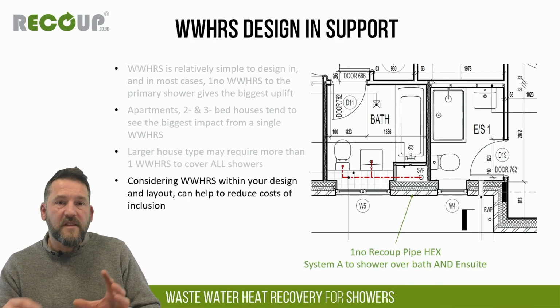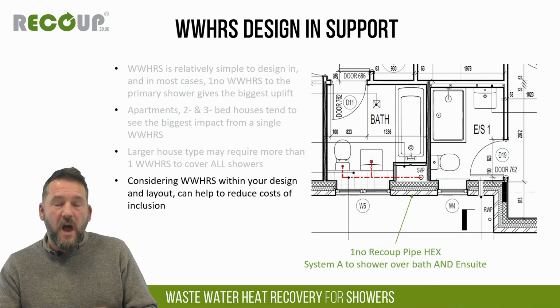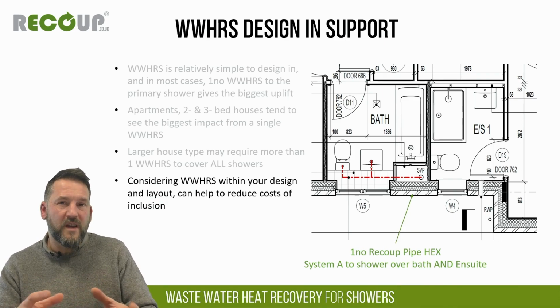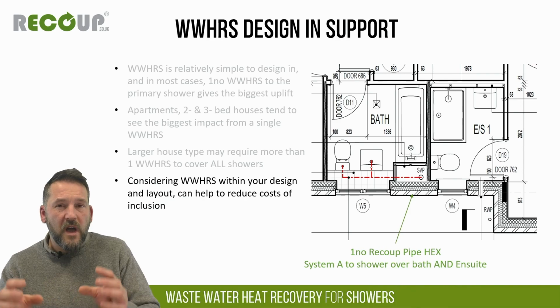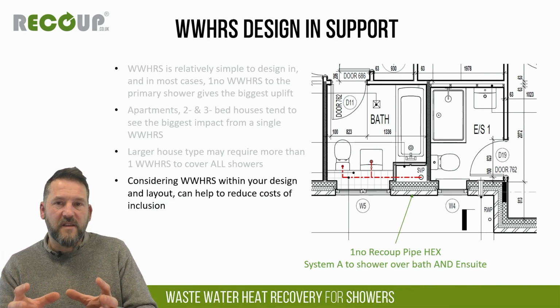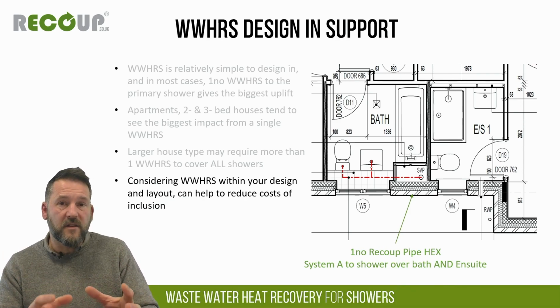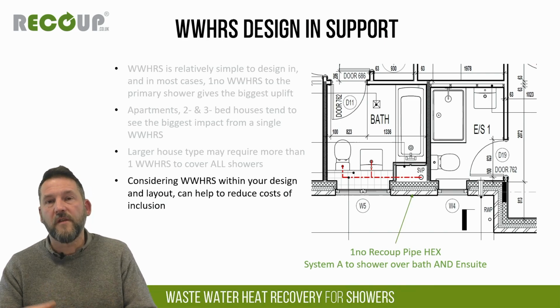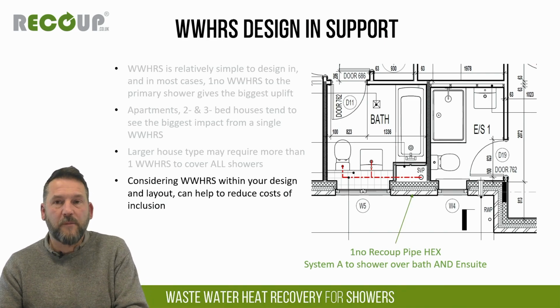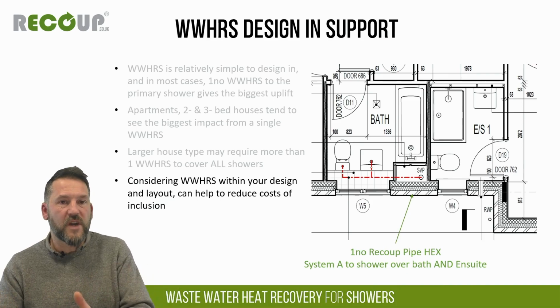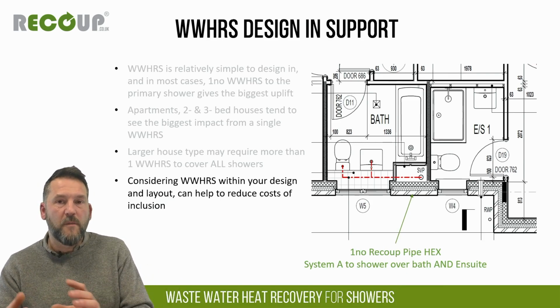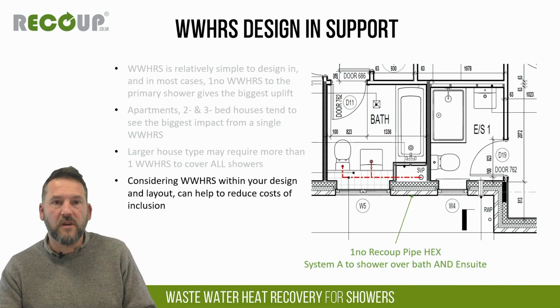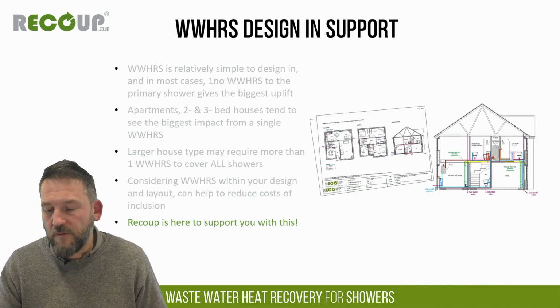And considering wastewater heat recovery early on, certainly if you engage with us early on, we can advise on tweaks and things that we know to make sure you get the best out of wastewater heat recovery, or certainly the least cost for wastewater heat recovery. So for instance, the obvious choice would be back-to-back bathrooms where you can run the shower, or maybe shower over bath, into a single pipe, and that will maximise the benefit but also reduce the installation cost as well. And as I said, we're here to support.